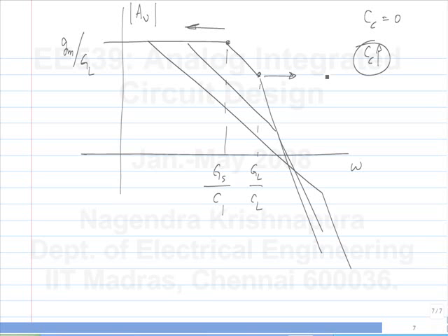Any questions on this? So again, as far as this assignment was concerned, it was more or less a practice for circuit analysis, but please do keep the result in mind because we will be using it repeatedly afterwards. And this phenomenon of one of the poles moving higher and the other one moving lower is known as pole splitting. So this is the basis for Miller compensation of op amps.